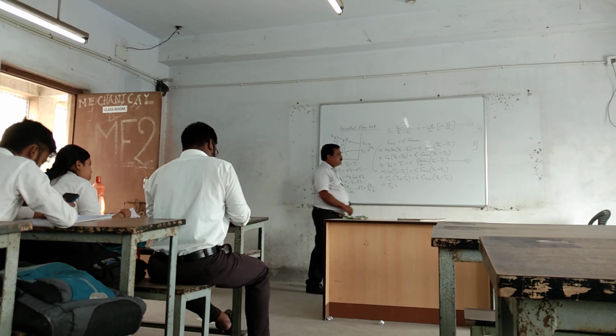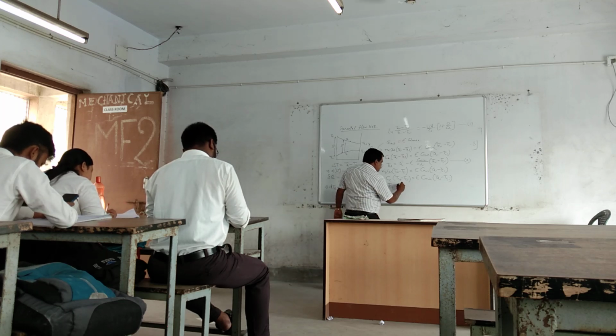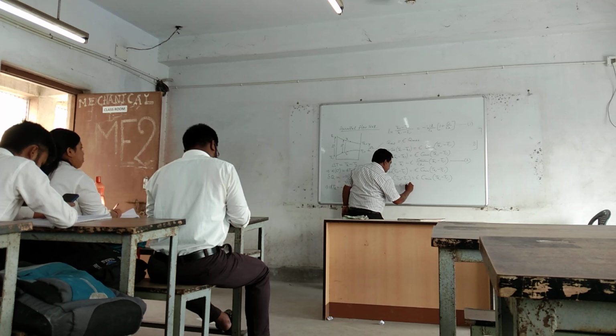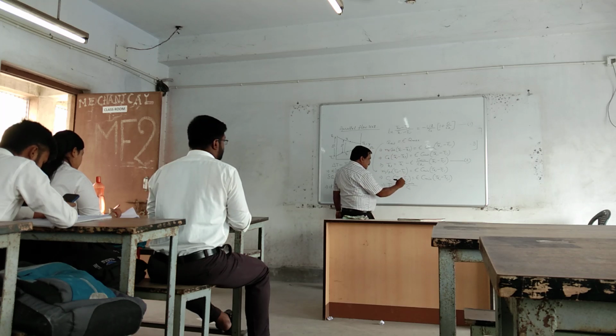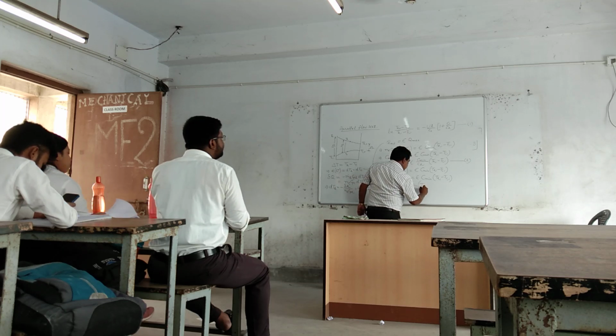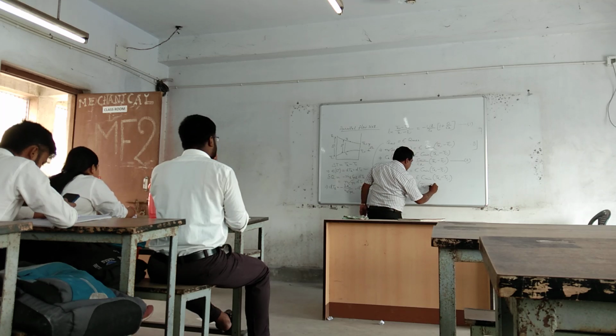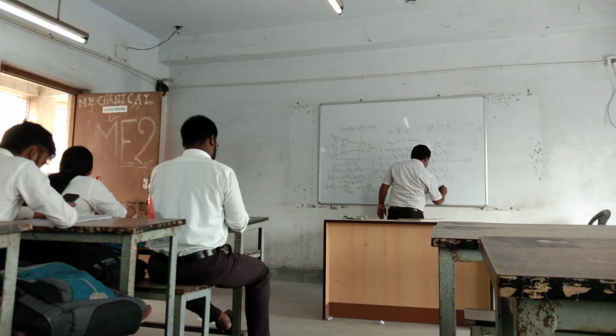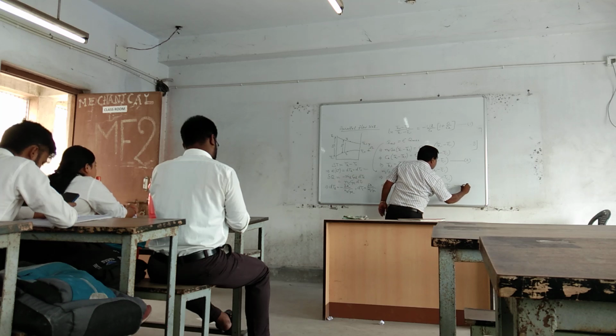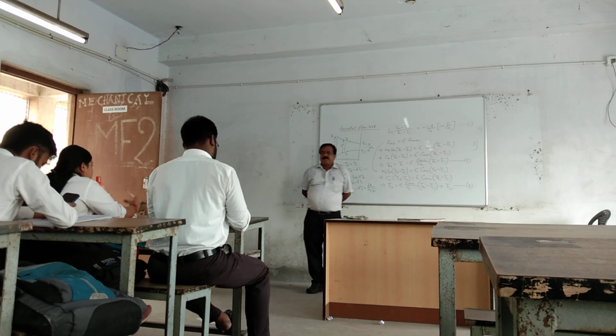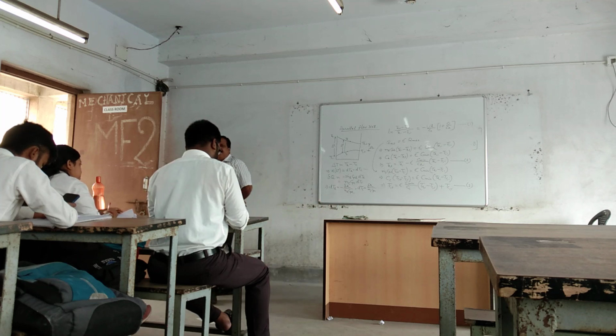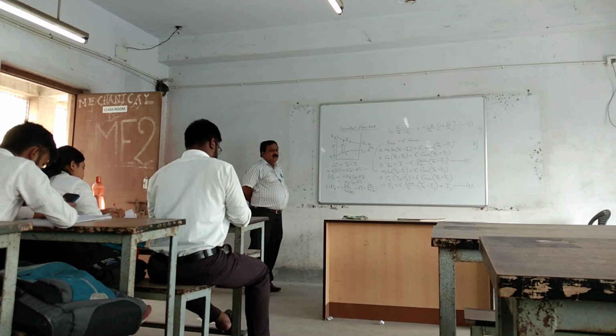What is TCO? That is epsilon C min by CC (THI minus TCI) plus TCI. Equation number 3. See, in equation number 3 there is also no outlet temperature, only the inlet temperatures, because only inlet temperatures are known to us.